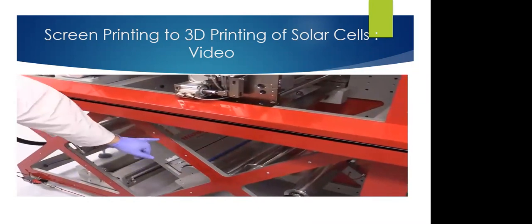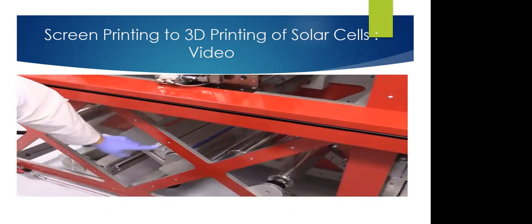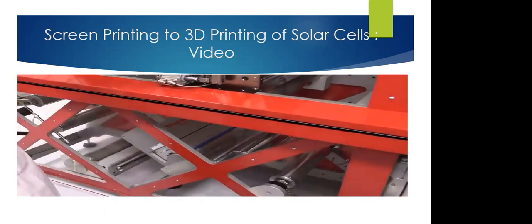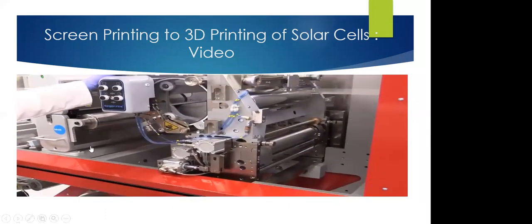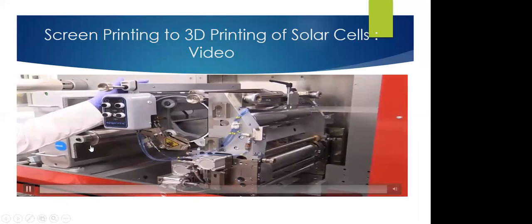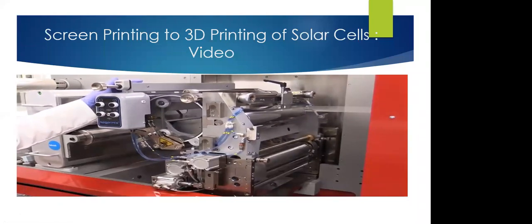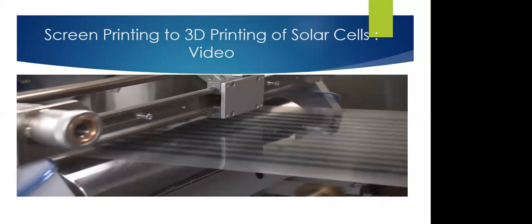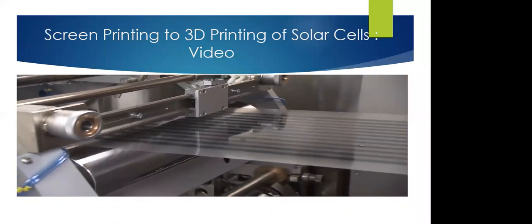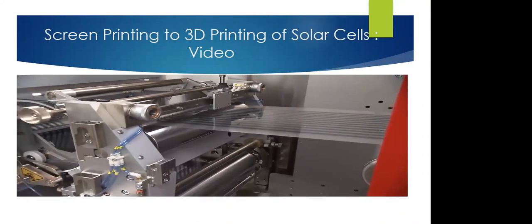After the corona plasma treatment, we're ready for our first printing step. So the film will pass through, up, and into the first print station. The print station we have here is a screen printing station. With this, you can put down patterned films, patterned electrode contacts, allowing you to set up individual cells along your roll. One primary printing mechanism that we use is rotary screen printing, which is very similar to silk screen printing that you use in applications such as printing t-shirts.